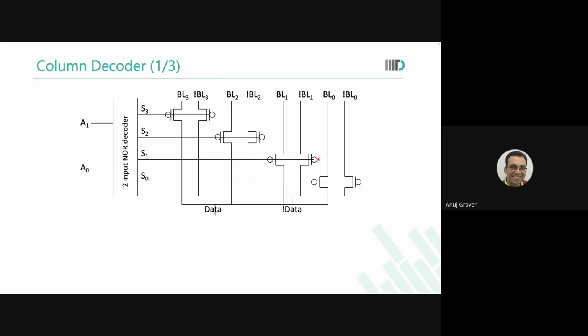Actually, suppose you have taken MUX 4, that means it will have 4 words. If we have suppose 2 bits in one word, we'll have 2 of these units in different IOs. Yes. So that is why when we said there is a 72-bit memory, there are 72 muxes there. This unit has to be repeated 72 times, once for every bit.